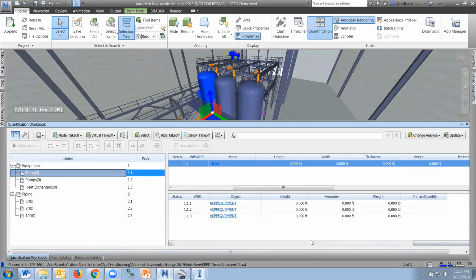You know, from some products like Revit, you'll see a lot more data that's already filled in. The knot that's tied between a product like Revit and Navisworks is very tight. It's very integrated. From the AutoCAD products, not so much. Now, this data is in the model. It's just not making its way to the takeoff. So, and you'll see that in an example I've got coming up.